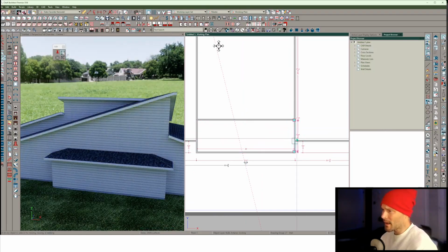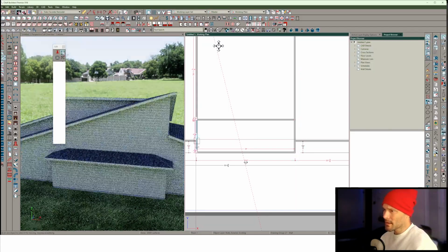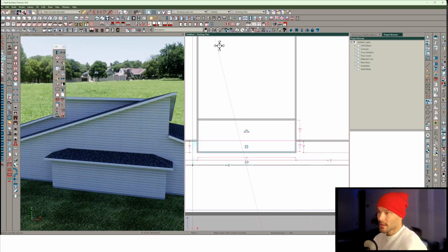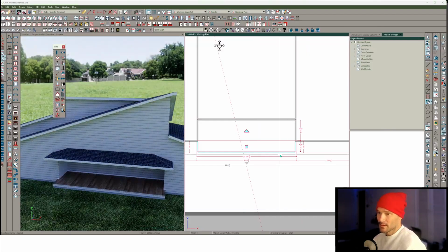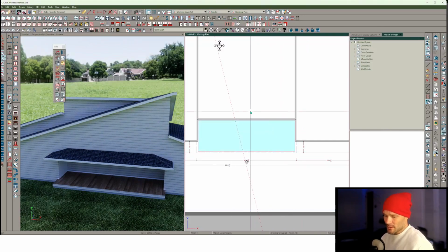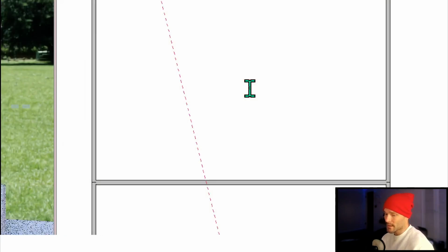And now I have a hotkey, so if I break these two segment walls, right, and then cycle back to my wall tool, shift marquee select these and then make them invisible walls, there we go, we're starting to create something. Now something I want to do here is I'm going to select this room that was now created, and I can open it up and say that it's roof group number 1 instead of number 0.